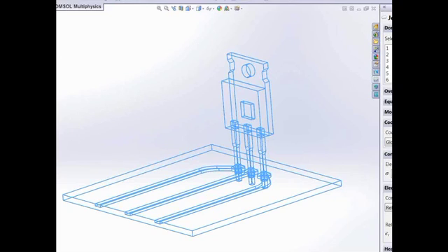If I look under the geometry node in the model tree, I can also see that there's a live link for SolidWorks node. You could look at this as the node that symbolizes the connection, the link between my COMSOL model and the SolidWorks file. And this contains also the dimension that I've selected from the SolidWorks design to be transferred to COMSOL.